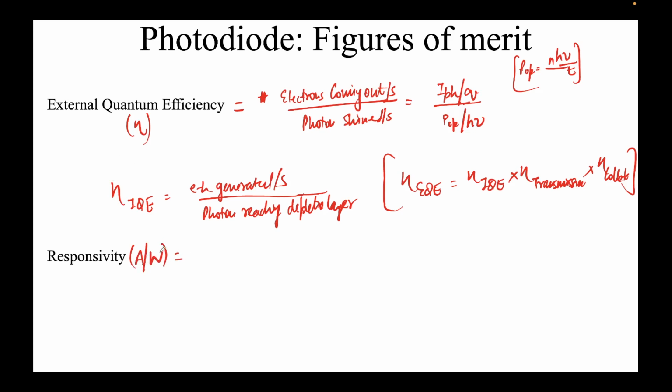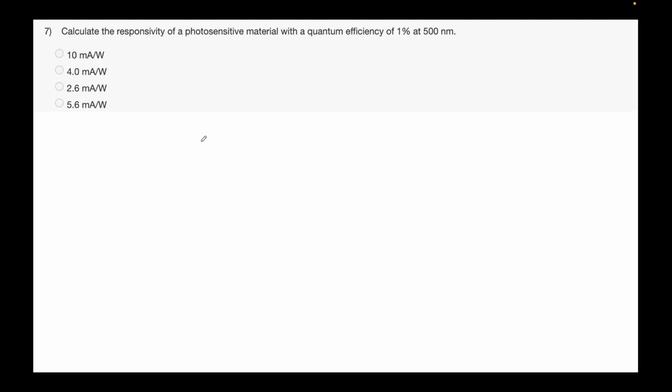What I mean is that these first two terms, I'm just trying to remove them out of the picture and leave just the h nu behind. So responsivity is nothing but the photocurrent that is coming out divided by the power that you are inserting. Simple as that. It's very straightforward. That's what I mean by how eta and responsivity are related, you'll see in this problem.